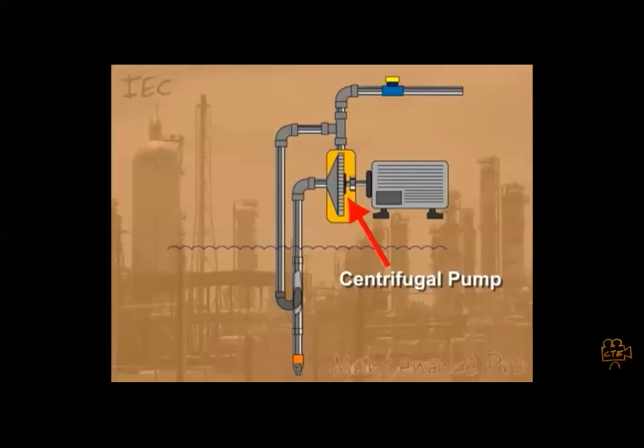Okay, so this is the diagram. Here you can see that some fluid is going upward and some is coming back to the bottom. That will create a tremendous amount of energy that the fluid has, and it will help to suck water from the water source. So this will help in the borewell and tube well. Ten years back, we used so many jet pumps for this. So this is the way.